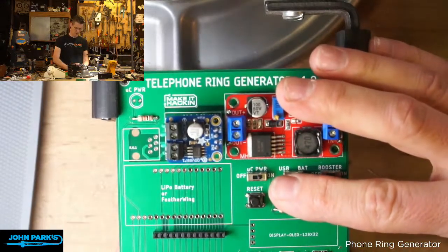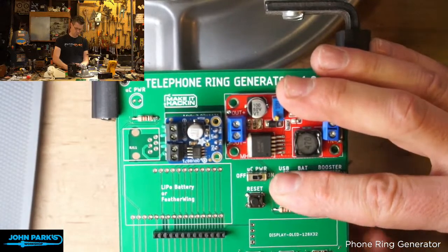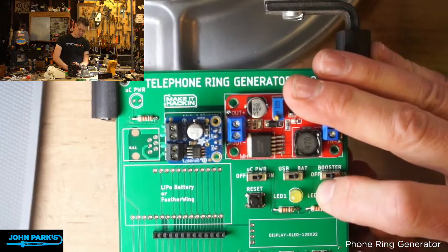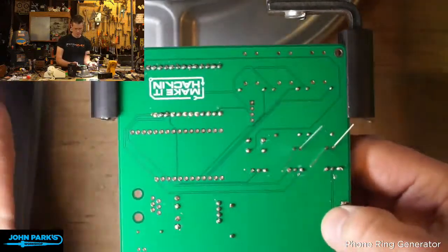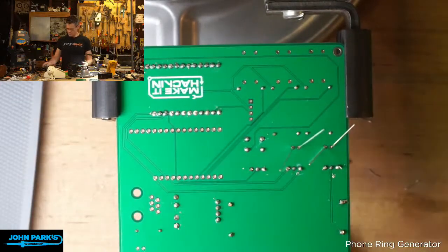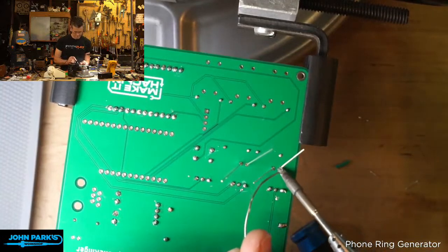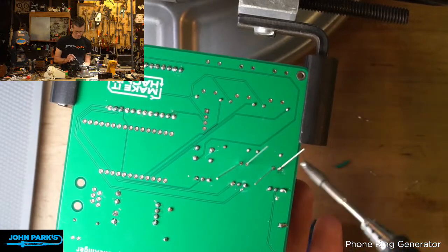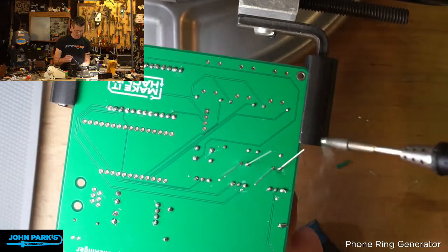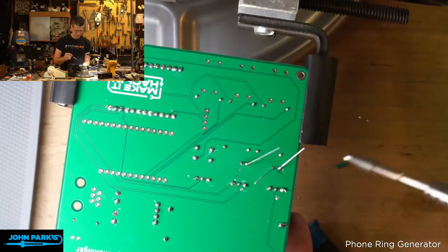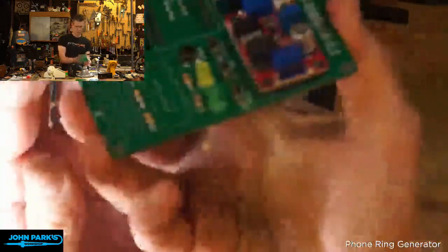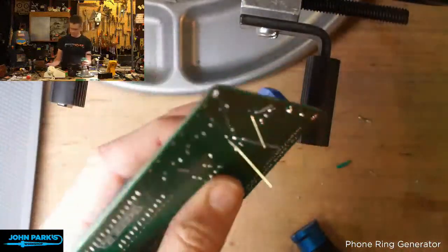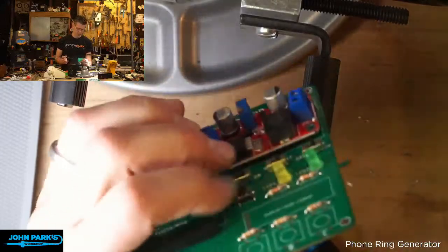So again, I'm just reaching underneath this and bending the legs a bit so it stays in place best we can when I flip it over. Again, blue tack or holding it or tape. Any strategies for that? Let's get just a bit of solder on one and then I'll square it up. Okay, again here I'll just tack that, then hold it, heat it again, and then press it up. Oops, oh, that's a mess. So let's flip that over and check. Those look janky, so I'm going to hold this one and look at it while I... There we go. That popped into place.